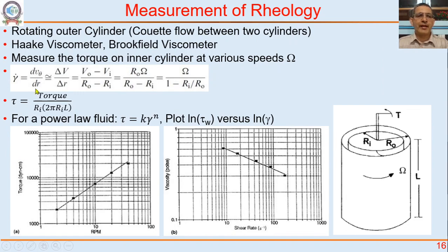Okay, let's try to look at how we measure all these viscosities. If you look at the laminar flow situations in the last lecture, wherever we calculated the forces, we found that the force was proportional to viscosity, and the strain rate was there, right? Whether it is Couette flow, Poiseuille flow, flow between two coaxially moving cylinders, a rotating cylinder, or capillary viscometry, in which a capillary tube is draining.